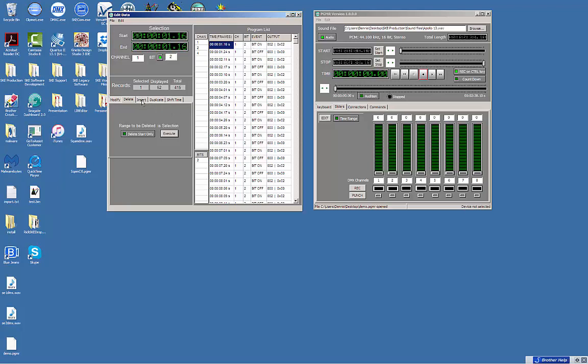Moving on to the insert function. I'm going to go ahead and select the slider data for an example. If you remember when I recorded the slider data, I didn't end on 0. I ended with a value of 10. And we can see that here as the last event in the whole frame has a value of 10. If we wanted to make that 0, we could, for example, go down to modify the output value, change that 10 to a 0, and go ahead and change it. Now the slider finishes with a 0 value.